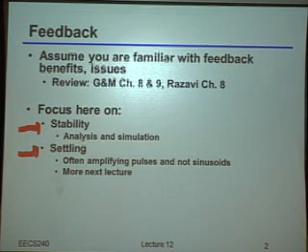What I mean by settling here is that oftentimes we're going to be using these feedback amplifiers in a context where we want to look in the time domain and make sure that our output voltage settles to a particular value very, very precisely. So in order to do that, we're going to have to think really carefully about the real time domain evolution of the signal, and basically how long you would wait, or equivalently, how much gain bandwidth you need to ensure you will settle to a certain voltage.